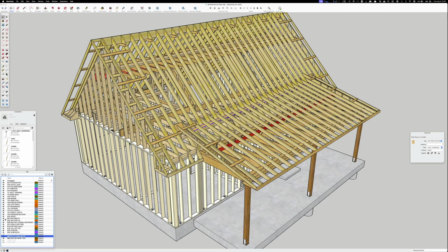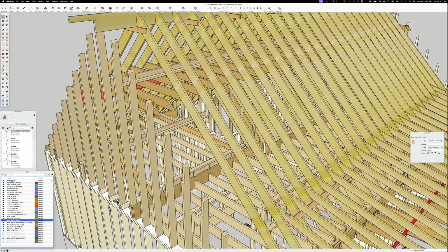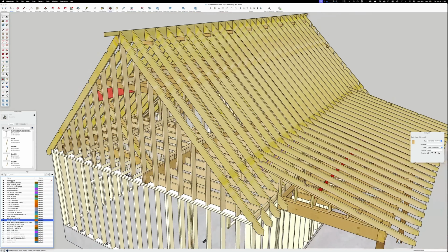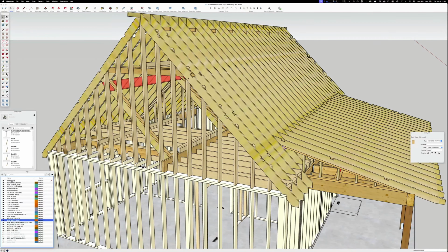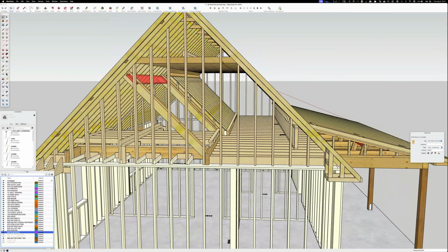This may seem old school, but I believe in it. This is how, when I first started framing, we would notch our rake wall studs. And then we would put the rafter down here and shoot into them. As you can see, it's pretty clean because the face of this is flush with this. And then when you do your subfascia, as you're plywooding this, you come up and you're actually nailing onto quite a bit of the rafter up underneath this 2x that's sticking out here.